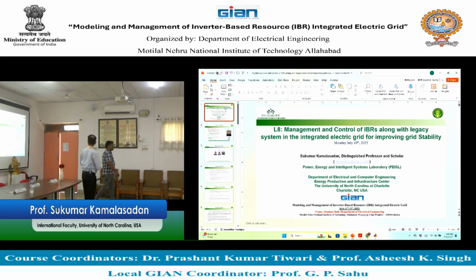The goal of the power flow and the optimal power flow is to give the set point or reference point for where the power grid operation should be in a steady state condition. For example, if you want to include integrated T&D with IBR, you will be able to get a set point for the operating conditions of inverters, or IBR, inverter based resources.